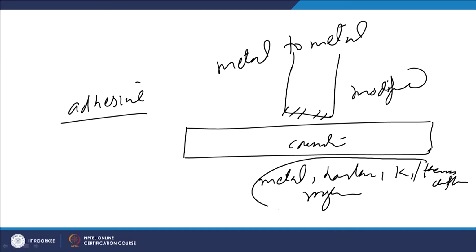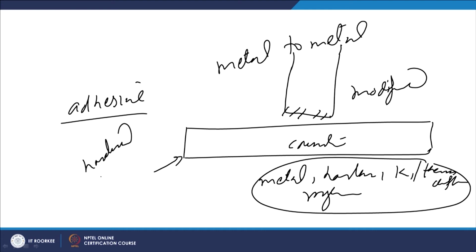All these affect the adhesive wear behavior significantly. So, the counter surface must be selected in light of the application against which wear behavior of the modified surfaces is to be checked. It may be hardened steel or it may be cast iron. As per the application, the suitable counter surface is selected so that it has the required hardness.